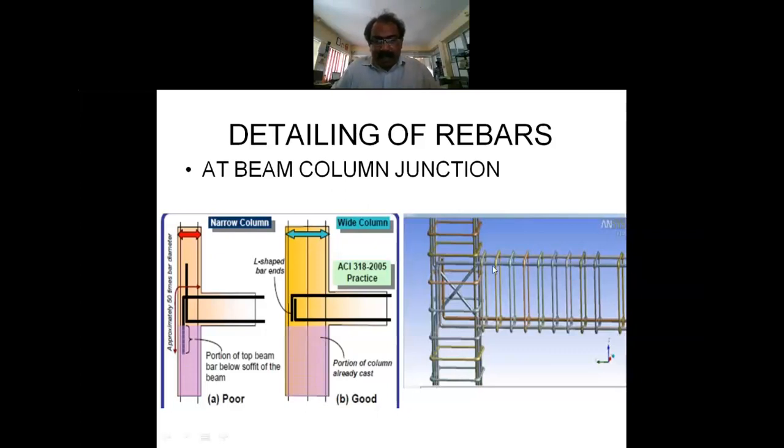Similarly, the top rods should come down, the bottom rods should go up. The rod in tension should go to compression, the rod in compression should go to tension. So lock like this. Then only it is 90% fixed. There are fixed and hinge supports, you may study them in your design classes. Even if you are doing like this, it is not 100% fixed, it's 90% fixed.